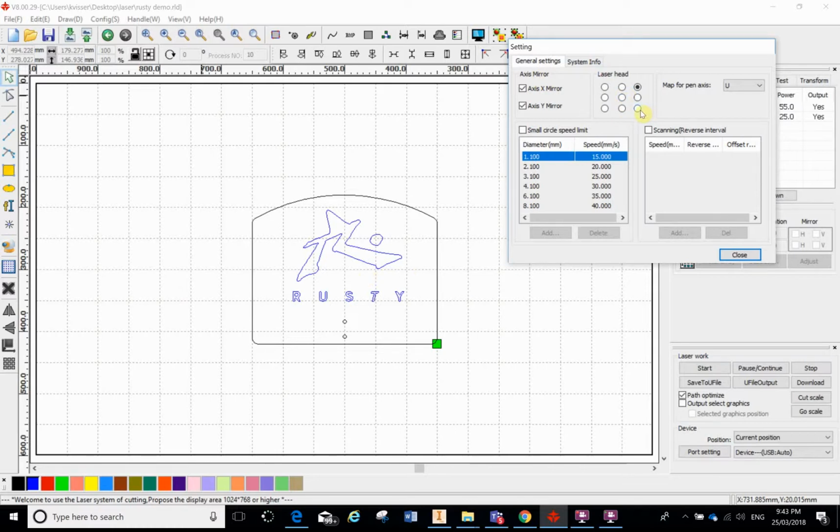We're going to work on this bottom right hand corner, and I want you guys to get in the habit of doing this, because that way when we scan our image, any smoke or resin coming out of the timber or material that we're using will get extracted across the sheet, because our fan is located at the back of the machine, so it's drawing all the fumes this way.